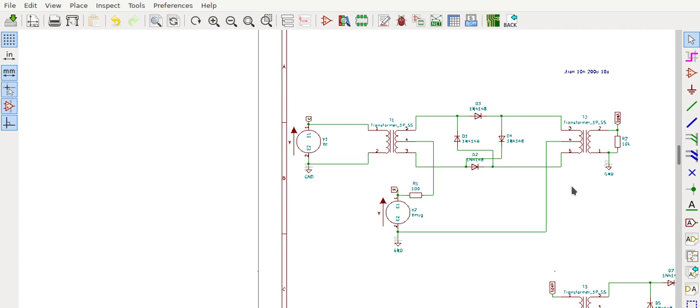So how the circuit works is, this is basically a sine wave, the carrier signal, and that is going to be coupled into the secondary part of this transformer. And this will provide 1 volt at this point when it is logical 1, and in that case the signal at these 2 points will be passed on directly to these 2 points.